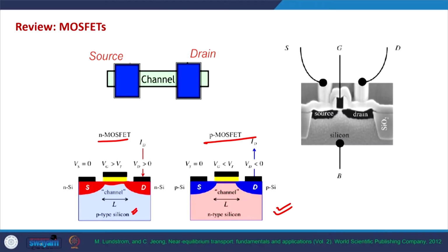By inversion layer we mean that originally this body or substrate is P-type silicon, but by the electric field produced due to the gate voltage, the electron concentration very close to the interface between the oxide and the body is so high that it behaves like an N-type material, and that is why there is a conduction pathway from the source side to the drain side. This is at the heart of the functioning of a MOSFET.